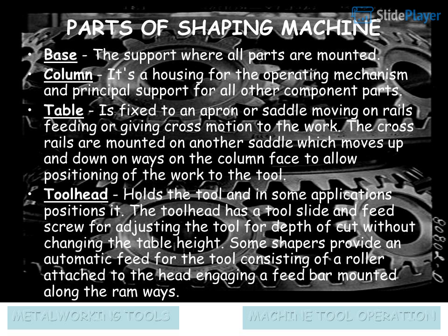Tool head, holds the tool and in some applications positions it. The tool head has a tool slide and feed screw for adjusting the tool for depth of cut without changing the table height. Some shapers provide an automatic feed for the tool consisting of a roller attached to the head engaging a feed bar mounted along the ram ways.